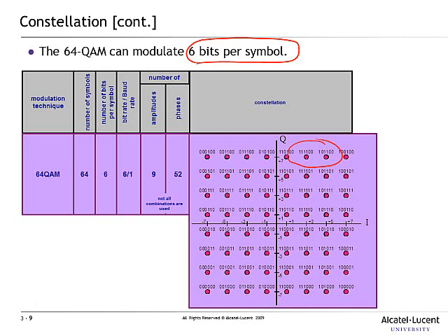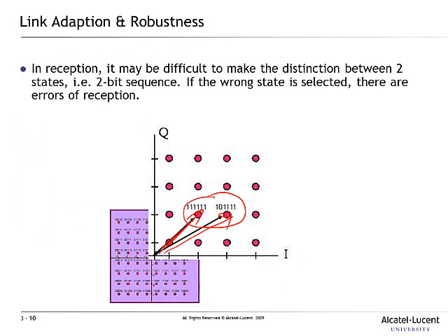Obviously, if the noise is very high, then first of all you should not be using something like 64 QAM. But if the noise does affect it, there should only be a 1 bit error. Okay, if the noise is very small level. And then there are other mechanisms inside LTE to deal with those kinds of 1 bit problems.